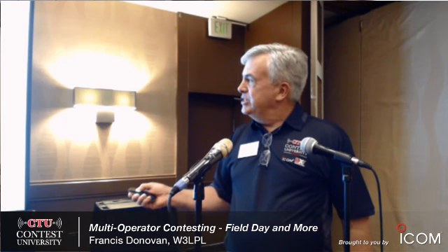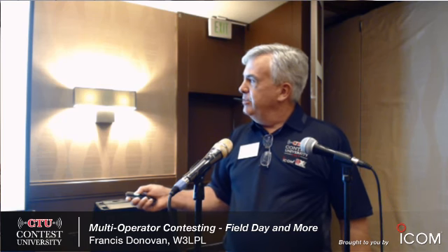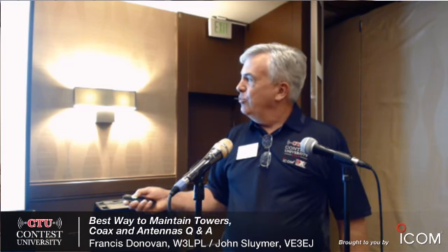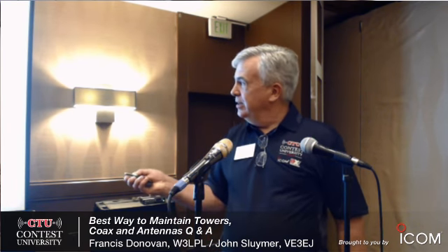A very simple Beverage antenna on 160 meters, 250 to 400 feet long, or a Beverage on the ground, typically 200 to 250 feet long. They have somewhat better RDF, 4 to 6 dB for a pretty short antenna, and a very, very simple antenna. There's hardly any antenna you could ever build simpler than a 250-foot piece of wire with a coax cable and a little transformer on one end and a resistor on the other end. Or you could just lay a piece of wire on the ground, and I'll show you some photographs of those.